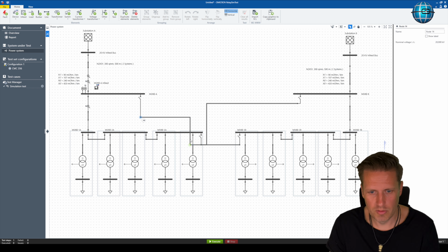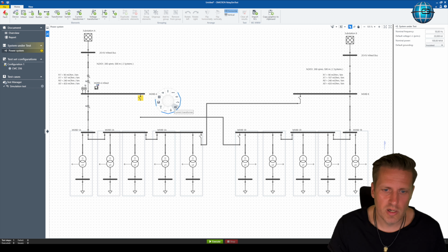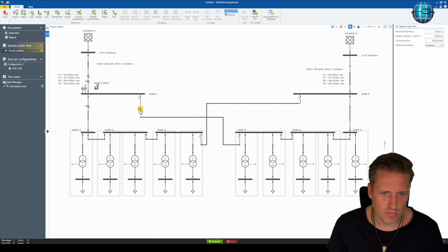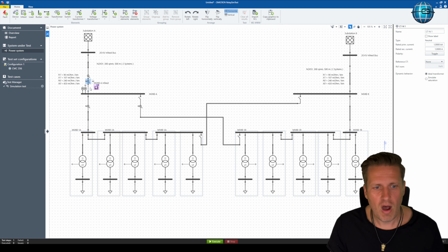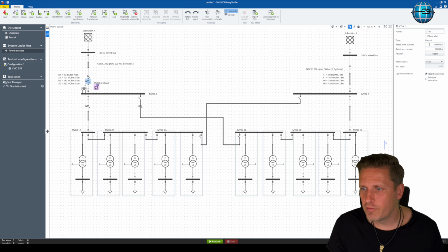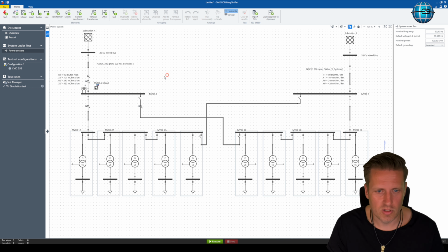Let's put this a little bit down and delete this area and add another split core transformer, toggle the earth, turn it around, and connect it as well. So what we have to do now is, of course, we need the proper rating for it. Oh, that's what we forgot for our first one here as well. We have here 60 amps by 1, okay? We just do a good job in putting all this 60 amps values here inside, okay?